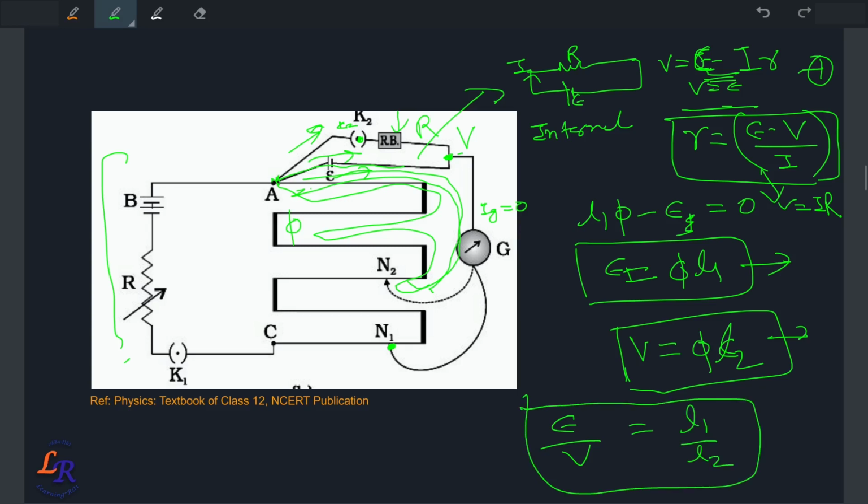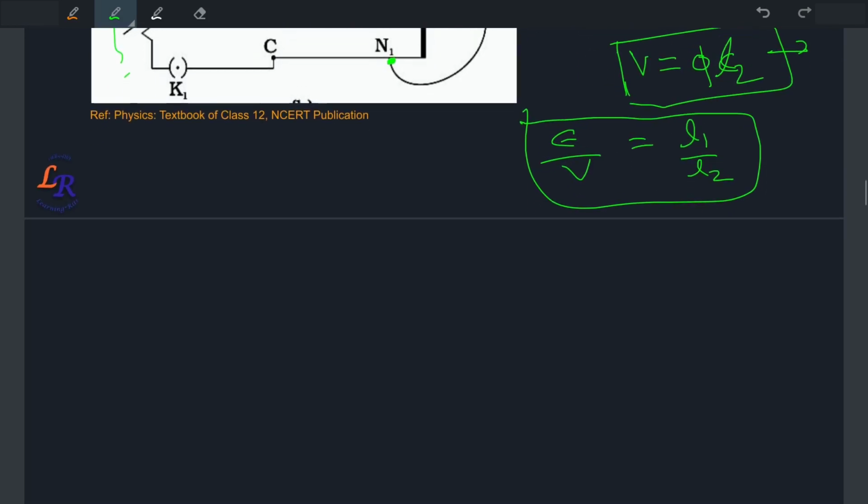Now, as I discussed, to find out the internal resistance, you can utilize that equation. Let's come back to that point again. Let's say the terminal voltage which we are talking about is something like this, right? The current I is flowing, and we know the terminal voltage between these two.